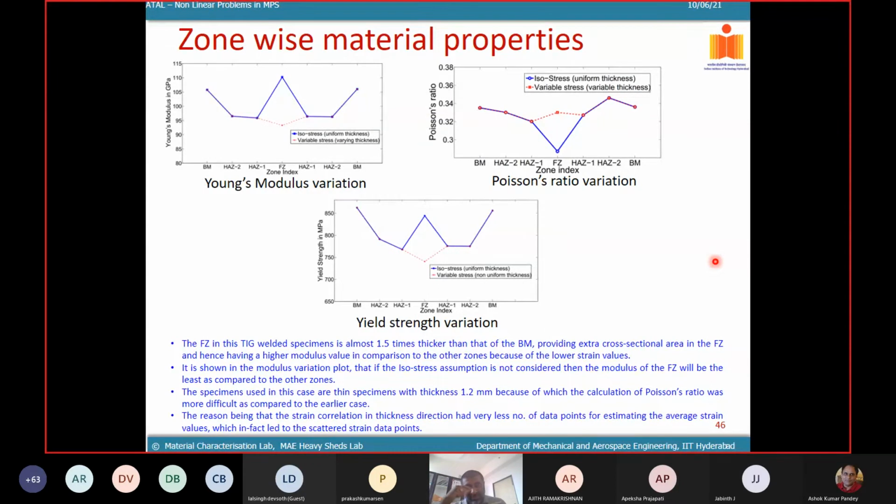Okay, but if you look at the literature, there is a considerable discussion whether after I weld, I remove the flushing of the material. That is the projection. Okay, the weld projection, I have to remove it, or I can retain it. Typically, they flush it if it's a thick plate. If it's a thin plate, they don't flush it because it can disturb the weld. For thin sample they don't flush it. For thick sample they flush it.